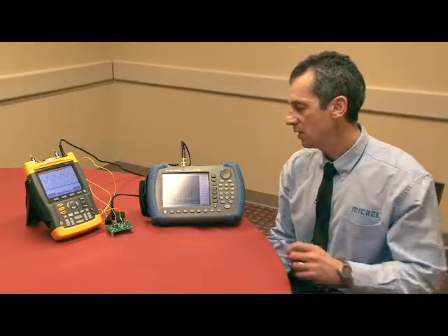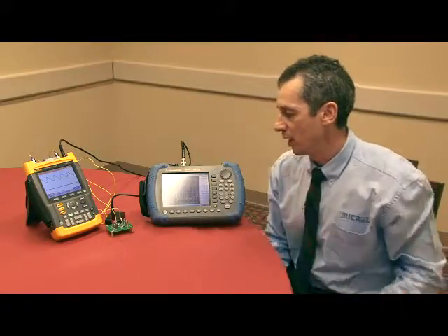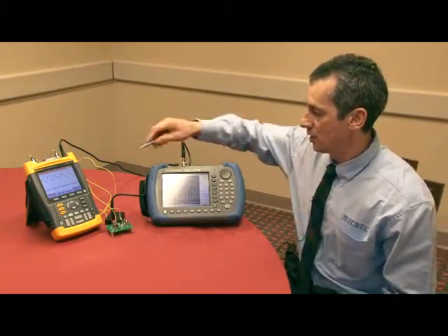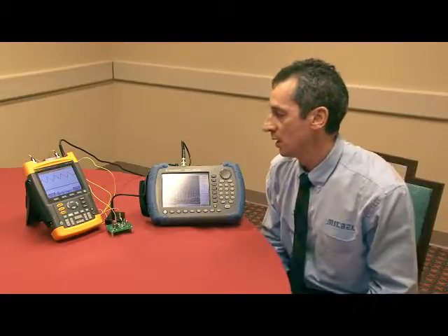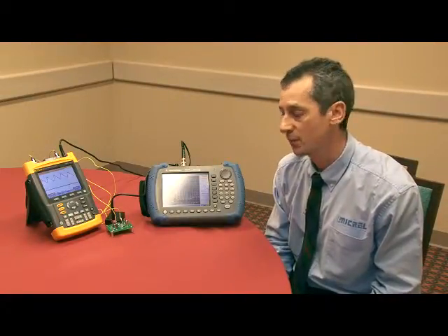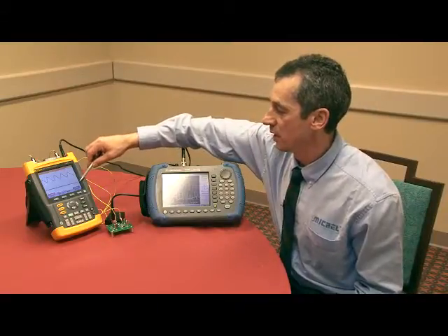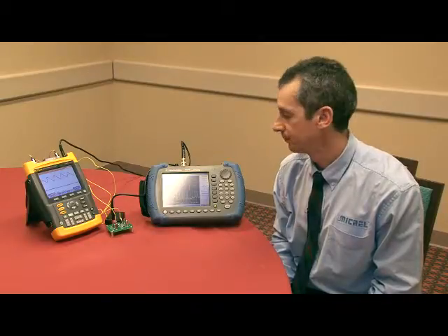I'd like to show you a demo board here today. On the left, we have a Micrel 23155 hyper light load switcher operating at 630 kilohertz, and it's operating in discontinuous mode. So it's producing a waveform over here of 25 millivolts peak-to-peak ripple in a sawtooth. You can see what the ripple blocker does below it here. It's really eliminating all that ripple. So essentially the ripple blocker is intended to eliminate ripple produced by a DC-DC converter.